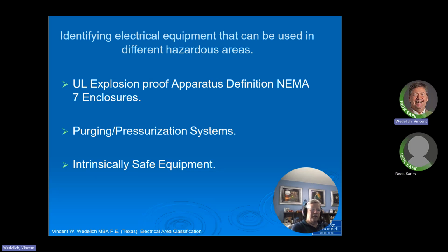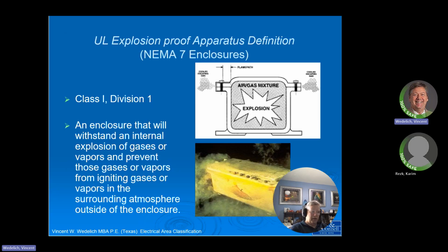Okay. So here they know the gas can seep in there. They know the box is in the gaseous area, but because it's purged, you can't create it; the gas can't even get into the arcing area, right? And then intrinsically safe areas, you're limiting the energy below a certain value. So believe it or not, these NEMA 7 boxes do explode, but they're still safe. They contain the explosion and they have a cooling effect, so by the time it gets outside, it'll actually cool the explosion, or the hot gases, to the point where it won't auto-ignite the air around it, right? The gas around it.